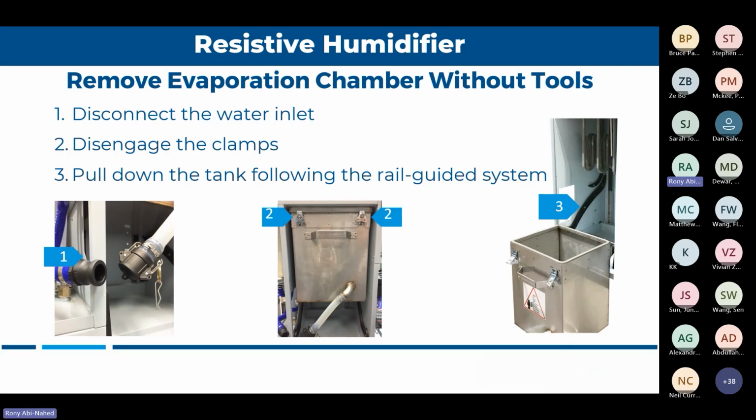Now, an interesting fact, to go back to the same example I spoke about, the paint job. The customer told me, oh, well, the scale is not falling from the heaters. I mean, definitely it will not fall from the heater if you're running the heater the whole day, because there's no time for the heaters to cool down to create this extra expansion and contraction movement. So for the heaters to literally move to let the scales fall down, they need to cool down and heat. If you're running the heater the whole day, the unit is not doing that. And that's why when you use city water, you drain every 4 to 6 hours to allow all the scales to go through.